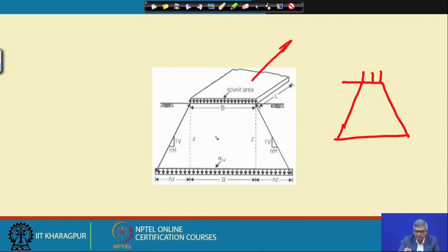In stronger soil the dispersion will be more, but when the soil is weak, the dispersion will be less. In most common practical work, we generally take one horizontal to two vertical, but it can be anything.